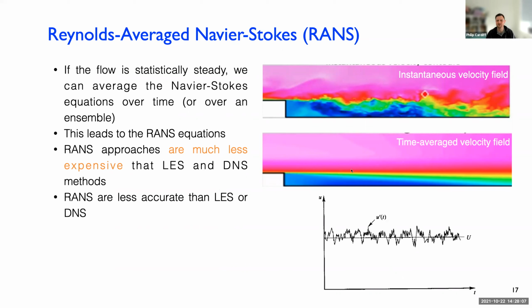time average flow field. It can be time average, or it can be what's known as ensemble average. They're conceptually two different things, but they're basically the same thing. Imagine that we ran this experiment multiple times, like hundreds or thousands of times. At any moment in time, like 1 second, we just take a screenshot of all the different flows from the true DNS solution, and then take the average of all of those. So at any moment in time, you could define what's known as an ensemble average. An ensemble just means you ran this test case loads of times, so you can take the average.